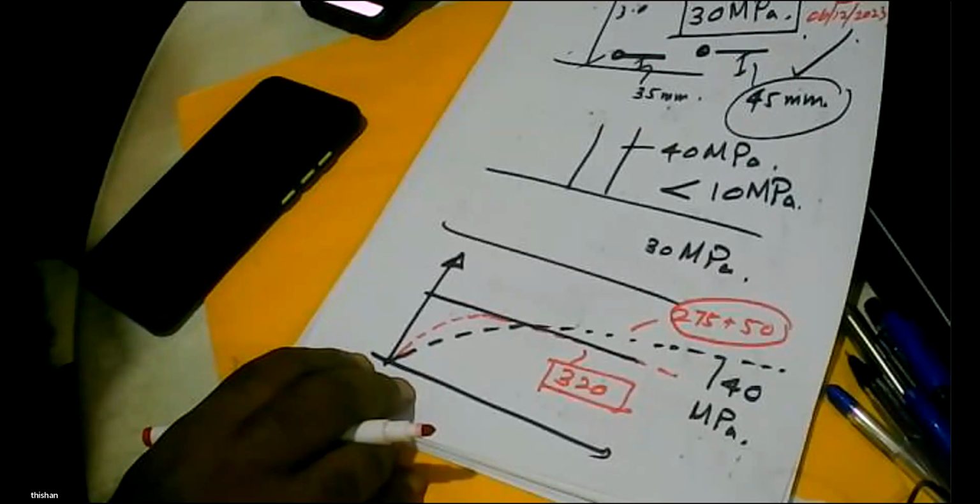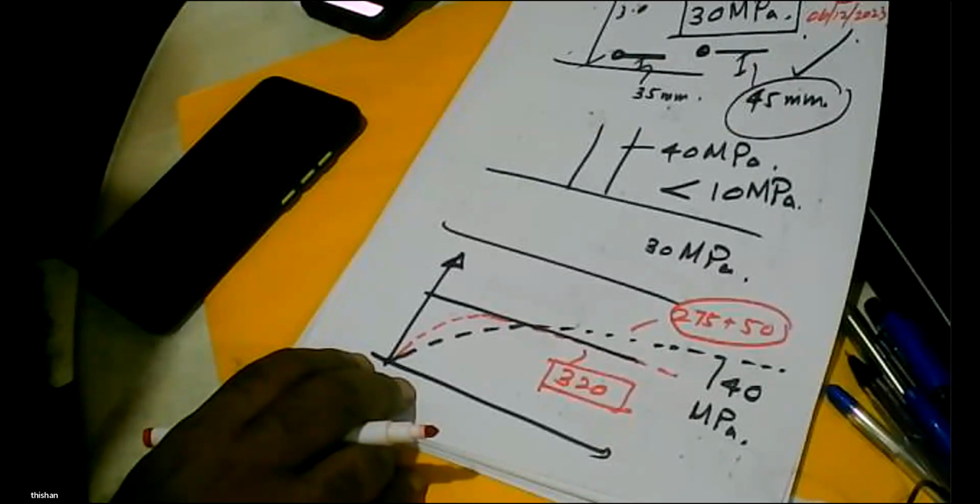You are creating a cover zone which is very dense, and when the cover zone is very dense, the pores are not connected. So the ingress of carbon dioxide into the concrete, with the reaction that we call carbonation, is very slow, very slow. Even after 100 years, you might still find the concrete is super strong and not affected at all, because the carbonation depths are very small. So that's why the curing of concrete is extremely important.